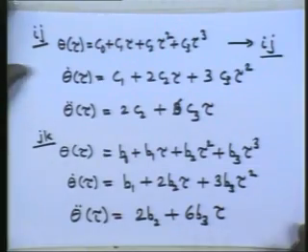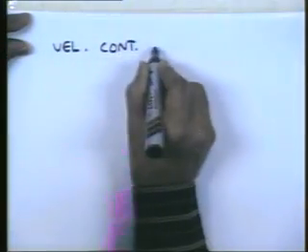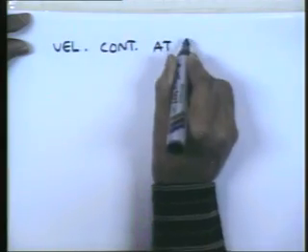So, we now have the relations for the velocities and accelerations. We will just stipulate the necessary smoothness constraints, that is, the velocity and acceleration be continuous at the position j. Let us see how those relations between the coefficients turn out to be. Velocity continuity at j means that the theta dots are the same.